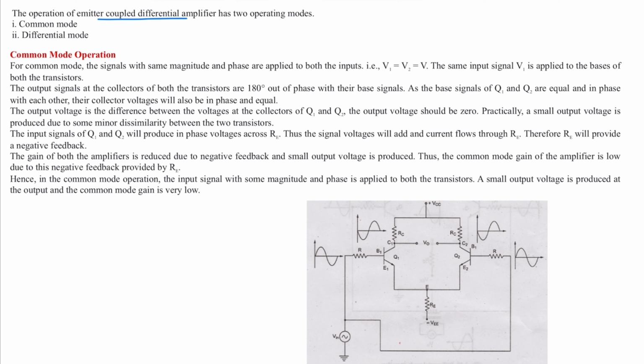So this is a common mode signal. This transistor provides 180-degree input signal. Both signals are given. We are getting the zero output. Ideal case of common mode differential amplifier output is zero. Here it is zero. V naught is zero. In differential mode,